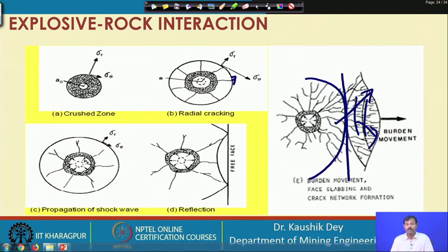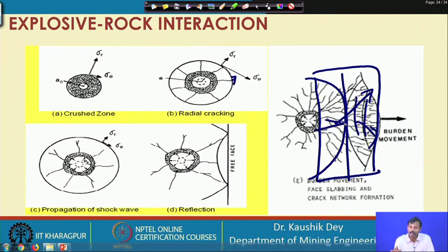The reason is that the gas produced is of limited quantity and limited pressure, and if there is a huge solid rock mass in front of the gas produced from the explosive detonation, it cannot throw that rock. So, we have to give some weak, fragmented rock mass at this position, some fragmented rock gathering, so that the generated gas can throw the fragmented rock in the front direction.